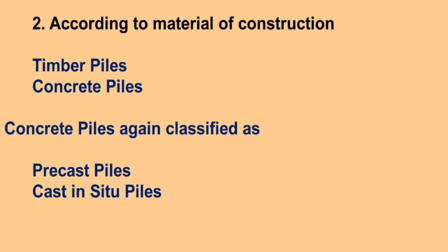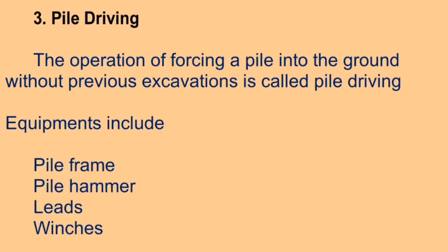Simplex pile, pedestal or bulb pile, Franki pile, Raymond concrete pile, sand piles, steel piles, etc. are the examples for cast in situ piles. And what is pile driving? The operation of forcing a pile into the ground without previous excavations is called pile driving. The equipment required for pile driving includes pile frame, pile hammer, leads, winches, etc.